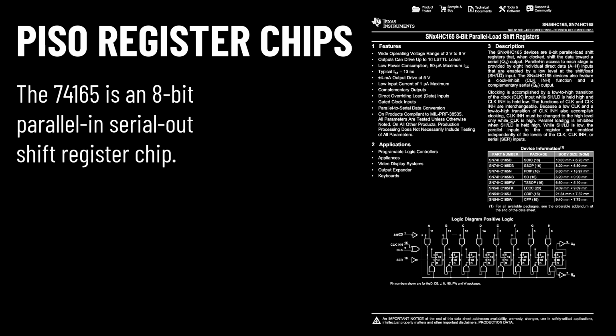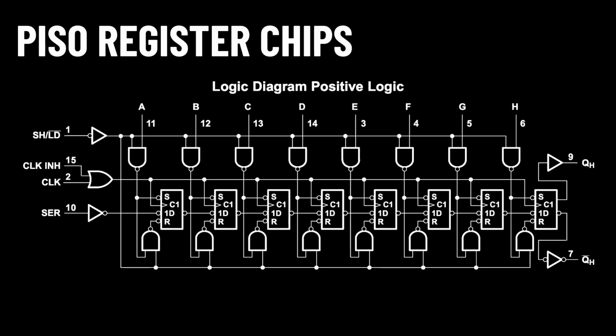If you take microcontrollers, we will use the 74165 to use a serial protocol to receive a byte of data from a dip switch and send it to a microcontroller using 1 data pin. Implementing this using individual D flip-flops would be slightly more complicated, as logic would need to be able to distinguish between the load and shift functions. We will do something similar to this in lab, and you can also figure out how the 74165 chip implements this by referring to the functional block diagram in the chip's datasheet.